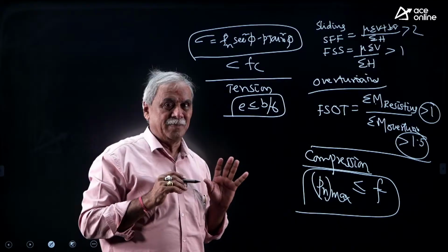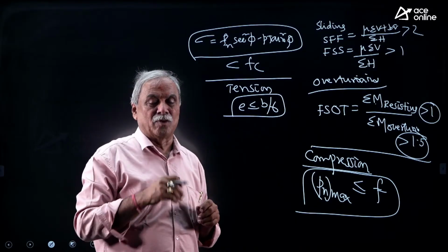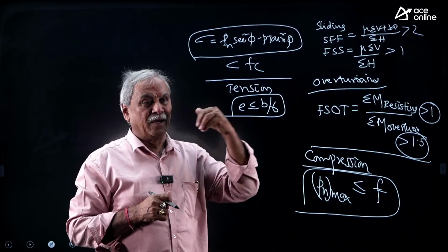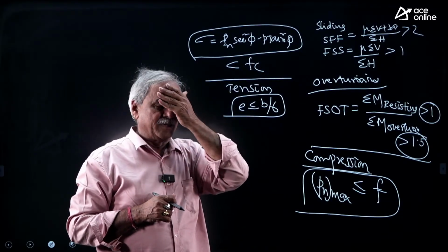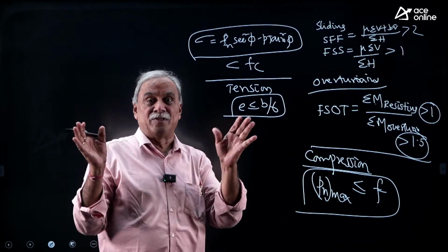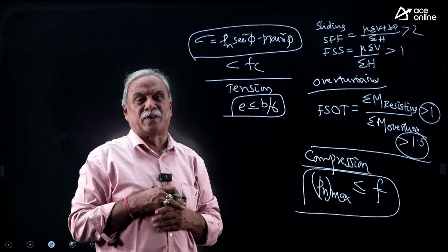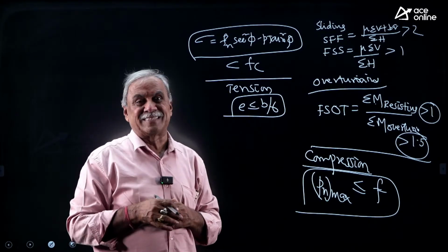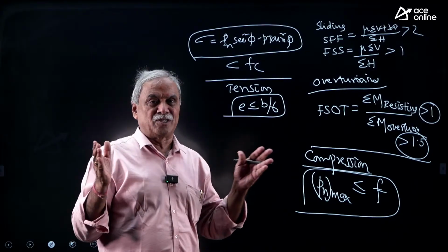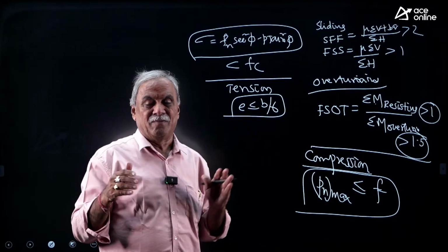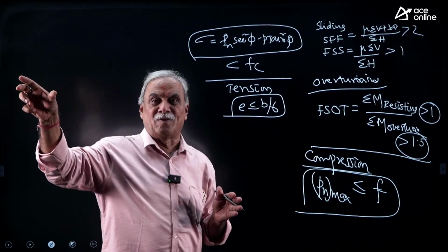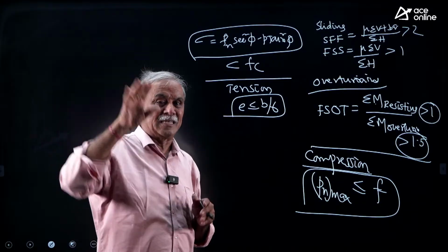Remember these points. Then regarding spillways, the overflow section of the dam is called spillway. We have two spillways. One is Ogee spillway. When the river width is around 1 kilometer, we can go for Ogee spillway. If the river is between two mountains having a width of around 100-150 meters, there is no other option but providing siphon spillway. Most prominently, the two spillways: Ogee spillway with a sufficient width of the river, and siphon spillway with a small width of the river around 100 meters, where the width of the spillway will be around 10 to 15 meters. That is called siphon spillway.